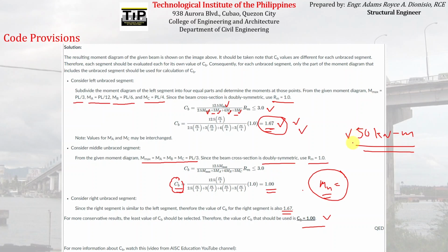Because of that, you can assure that the load will not induce a moment greater than the declared capacity, even if the true capacity is larger than the declared. So with that, you can have an allowance. And we want that. We always want that. For every design that we do, we want to impose an allowance for uncertainties, because there is no certainty in design.